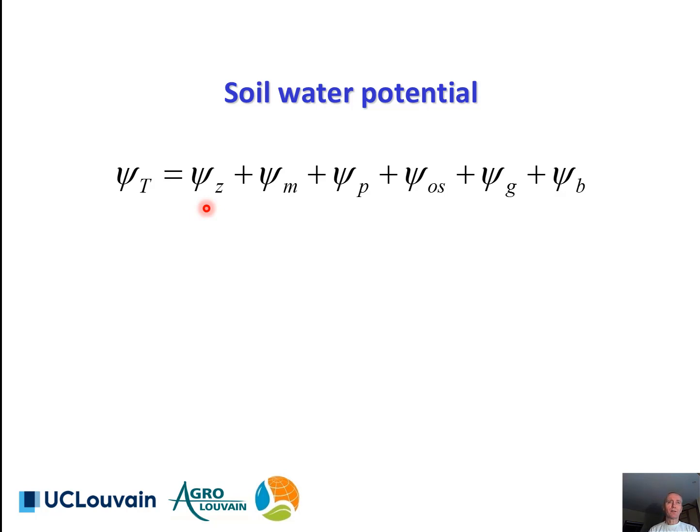Yet there are other forces that are exerted on the water particle in the soil. The particularity of many soil systems is that the pore space is not always completely filled with water. Soils are therefore often unsaturated with water, and in such cases, specific forces develop at the soil-liquid air interface that aim at maintaining the integrity of this interface. It results in capillarity forces. These forces aim at maintaining the interface between water and air, and result in the retention of water in small pores.